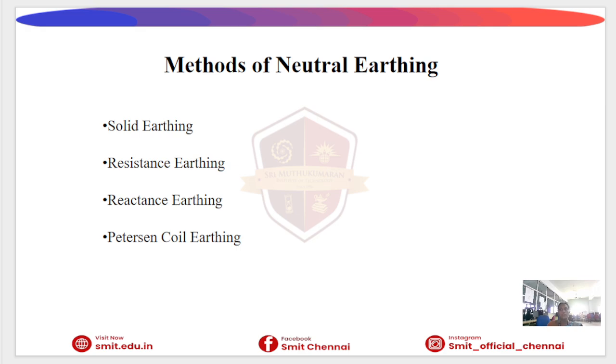Then what are the methods of neutral earthing? The different methods of neutral earthing are used depending on system requirements. First one, solid earthing, resistance earthing, reactance earthing, Peterson coil or arc suppression coil earthing.